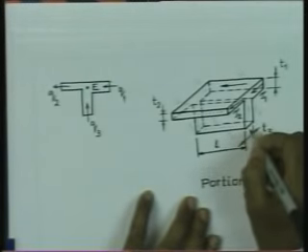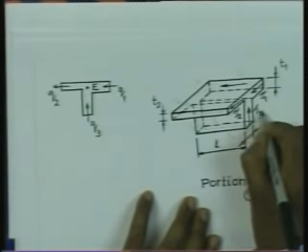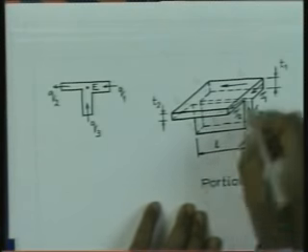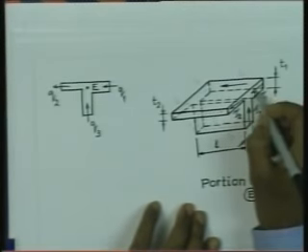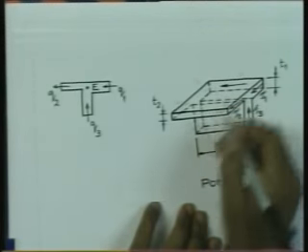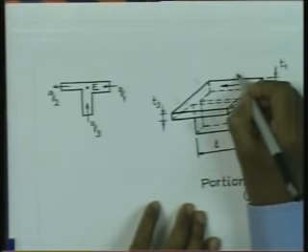This thickness is equal to T3 and the flow is Q3, and therefore the flow direction is this. We would have a shear stress acting like this, tau 3. If this is the shear stress acting here, then on this vertical face you are going to get stress acting like that, and this is also of magnitude equal to tau 1.